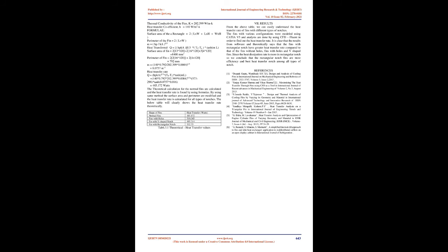The following graph represents the changes in the temperature of the fins under the same operating conditions. After the analysis is done, the results are seen in CFD post-processing. By choosing the domain, the results are seen by means of vectors and contour diagrams. The following images show the temperature contour of various notches and the results are given below.